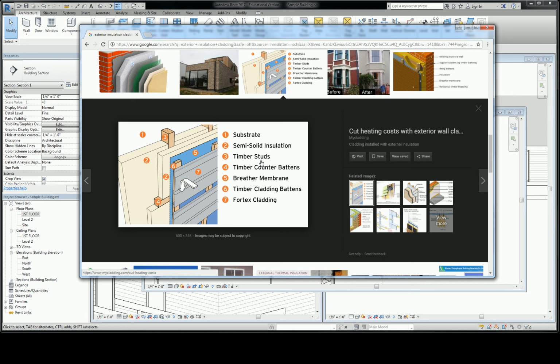Those are all going to be families, not system families, that you create that interact with those system families. So if you want to put a window in a wall, that's a family that interacts with and modifies a system family. Does that make sense? How would it be different if you had your own custom wall family and then you added a window to it? Would it be any different? No, it wouldn't be any different. In fact, you probably wouldn't be able to get the hosted families to interact with it the same way that you would with the Revit hard-coded system families. What do you mean by that? Because you won't be able to wall host.